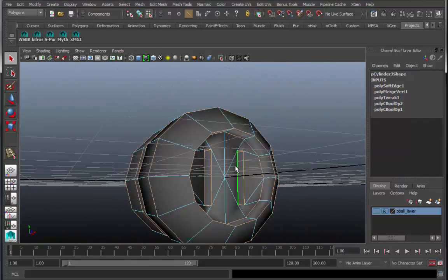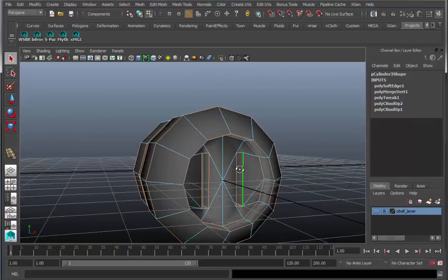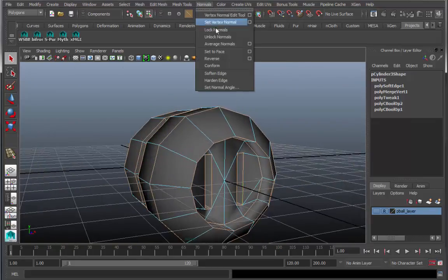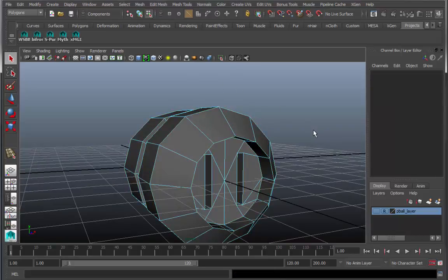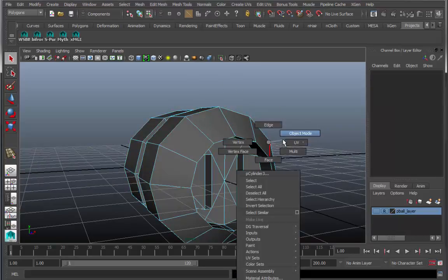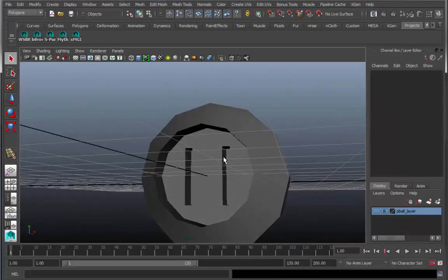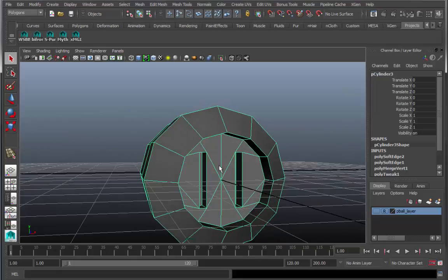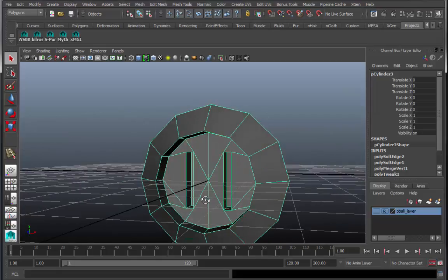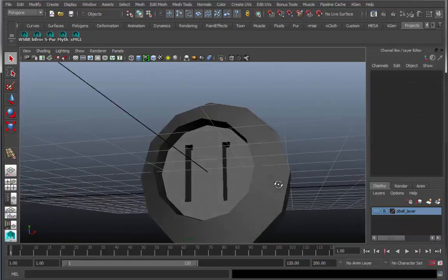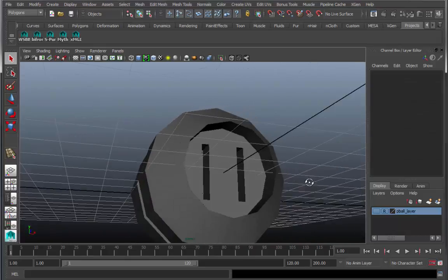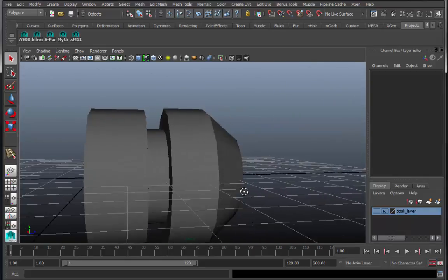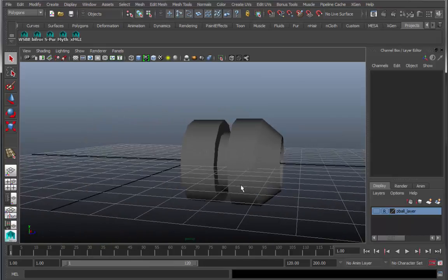and in shaded mode I want to have these now hardened and it looks wonderful. So this face that I was talking about, if I had inadvertently grabbed any of these edges and hardened them, you'd see that weird breaking. Those must remain flush. They must remain smooth. The interior also is pretty visible because of all the hard edges of the normals in there. And the doorknob looks pretty good.